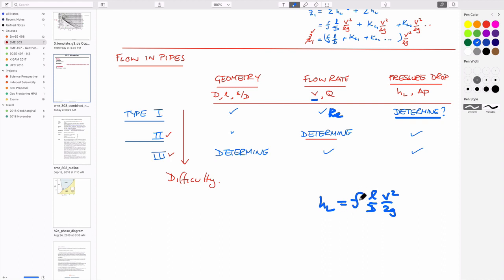It's a function of velocity for a smooth pipe or in the laminar regime, and so you can calculate it in one step altogether. And in the turbulent regime and for rough pipes, it's not a function of roughness at all, it's just a single number that you'd know anyway. So this type 1 thing is the easiest one to get.